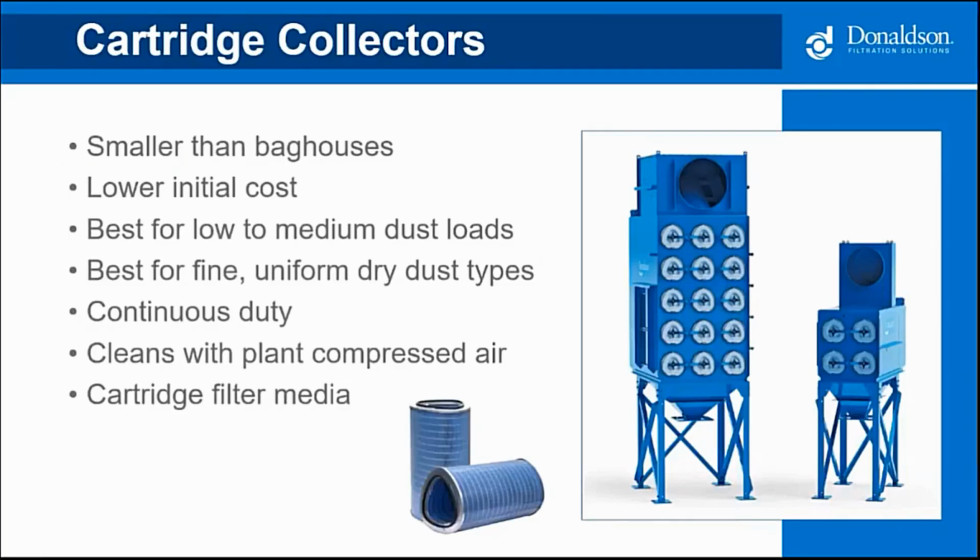I want to preface one thing. Donaldson Company, we manufacture with the widest and deepest product line. We make cartridge collectors, we make bag houses, we make cyclones, we make mist collectors. So when you come to us and you say, I have weld fume, our number one recommendation for this application is a cartridge collector, and we're going to explain the reasons why.